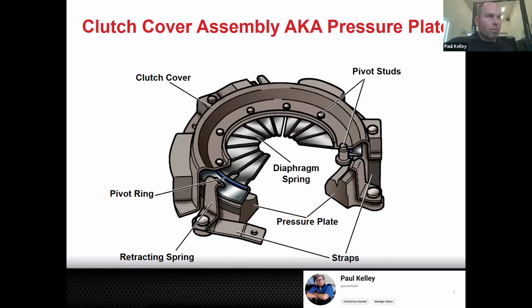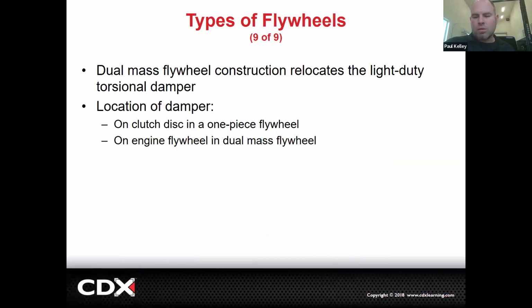And generally, if we're worried about this, it's either a damaged pressure plate friction surface, probably most common, or one of the most important, an issue with the diaphragm springs. So by the time you go to do a clutch, that spring has been flexed hundreds of thousands of times. So we'd expect the spring to have some problems, and also the pressure plate friction surface is going to have some problems. And that's why we do that as part of the clutch kit.